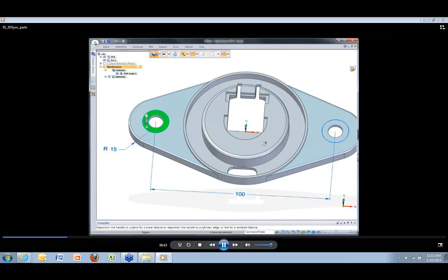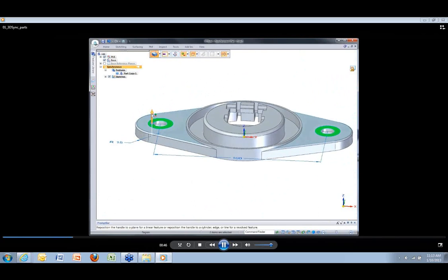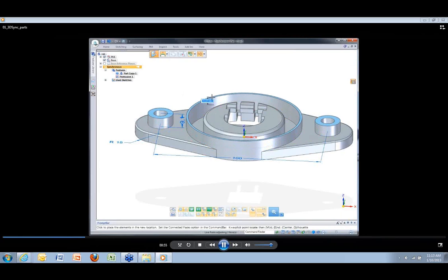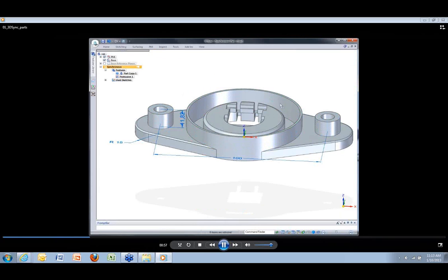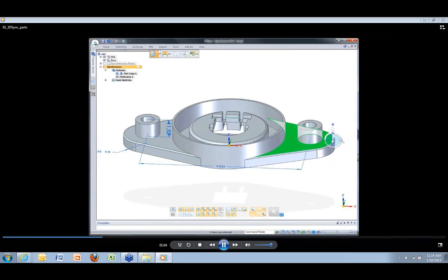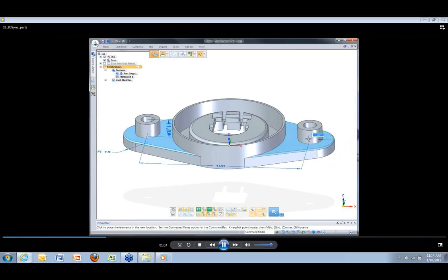Next, we'll quickly generate new 3D geometry from a familiar 2D sketch, resulting in a couple of new mounting bosses, their height driven by existing geometry. As the center face is edited, the mounting bosses update. Faces can also be rotated, and live rules unique to Synchronous technology find and change symmetric counterparts, ensuring the original design intent is kept.